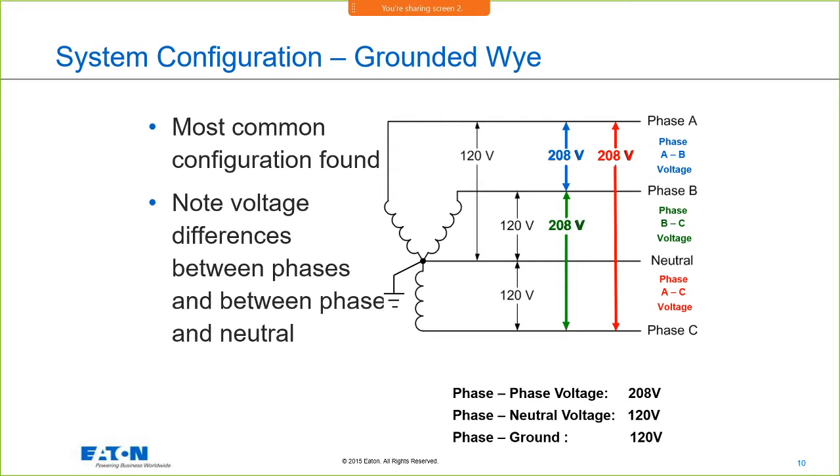And if you think about a circuit breaker, say a breaker with a rating of 120/208, or 120/240 volt, a slash rated breaker, that slash rating tells me that I can interrupt the currents at the 120 volt level, and I can interrupt the line-to-line short circuit currents when I have 208 volts applied across that circuit breaker.